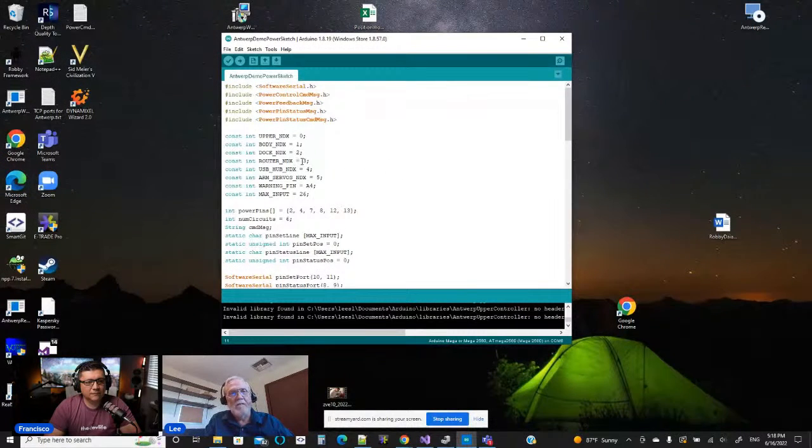and then it's providing a feedback message back. One thing I do want to look at real quickly here is these two header files, power control command message and power feedback message. These are header files that define little model classes that match message schemas for messages coming into the card and coming back from the card. The power control command message is for messages coming down from what we call the master control program, which is the C# program you write to actually talk to the network we're going to build. And then the power feedback message is a response message that comes back from the Arduino card to the MCP.